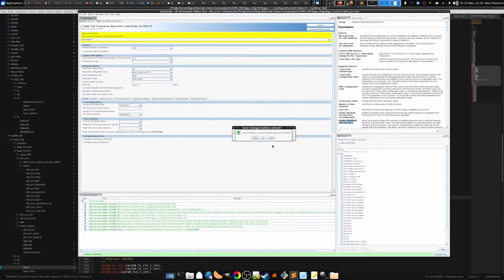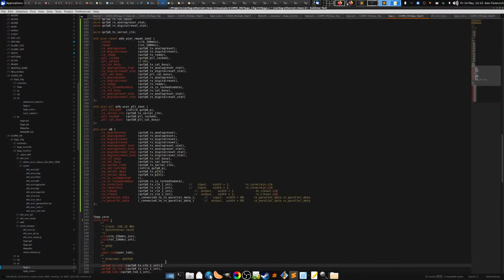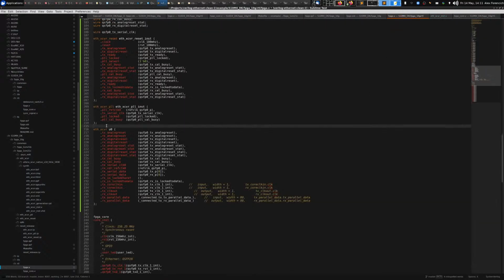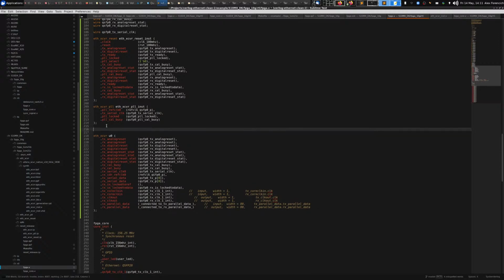Oh, and I will also mention that this does tell you what the PLL configuration needs to be. The external PLL must be set up for 5156.25 megahertz. So we didn't necessarily need to compute it, but because this thing was being annoying, that made things a little bit more expedient. All right, let me see if this was updated. Nope, that'll be updated in a minute. Okay, so now what we need to define are the signals that connect between the transceiver and the PHY instance.